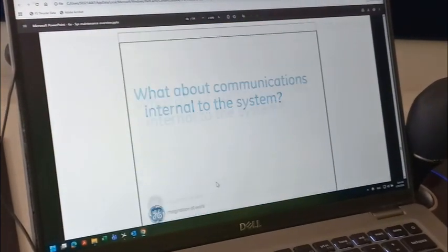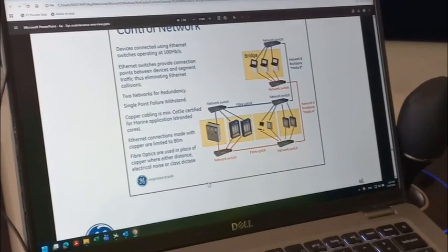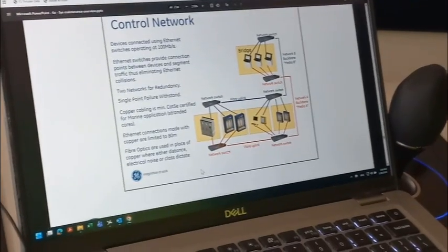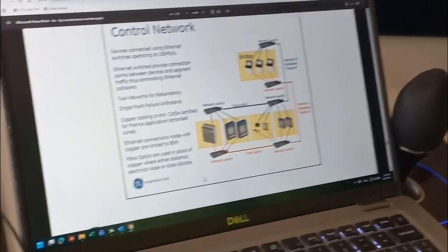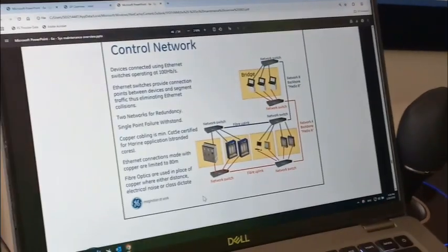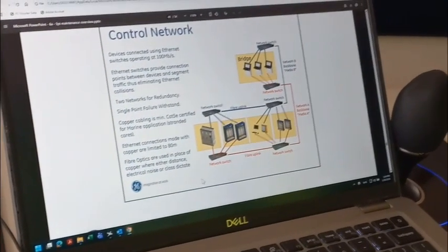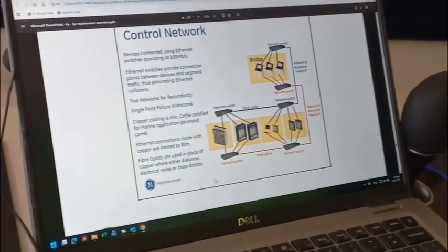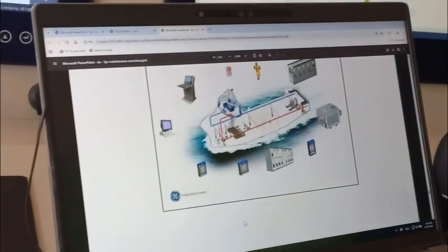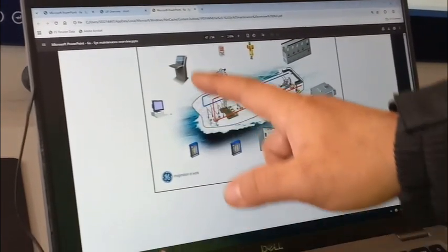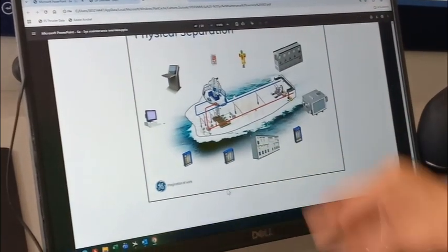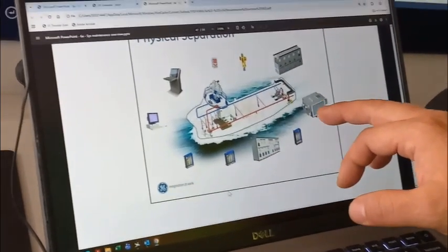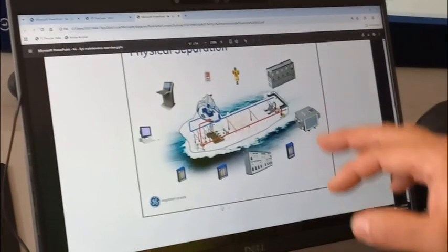Okay, that's the network A and B. Normally we have two switches to have the control network A and then a backup control network B. If you fail A, you will still have the backup network B to have all the nodes connected. You will not lose a single piece of equipment. That's a big project with all the DP automation, a few stations, and even the alarm, PMS, switchboard, drives, power switch.